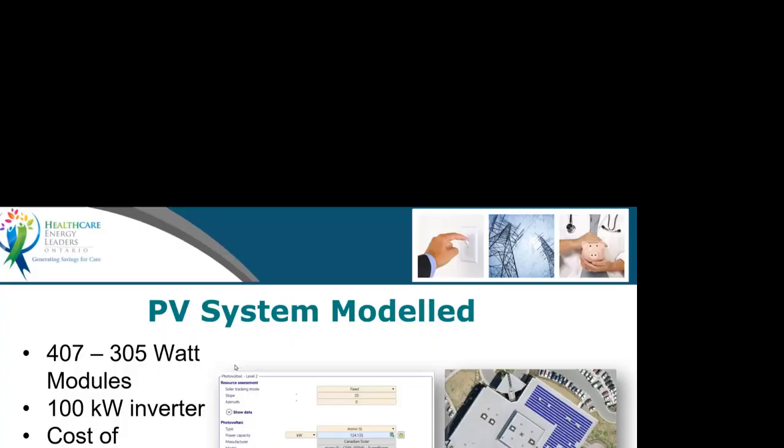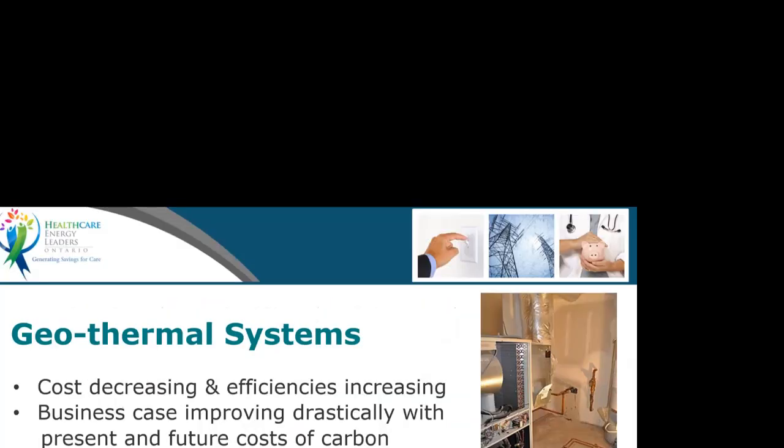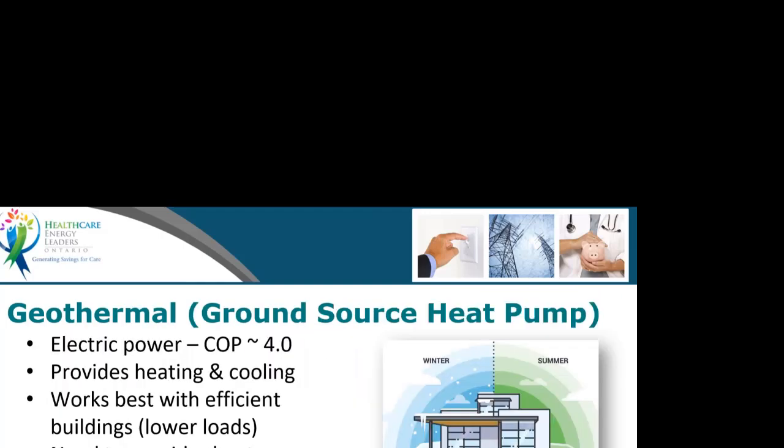Oh, this is one of my interesting ones. Geothermal systems, right? So here what we're doing is we're using heat from the ground, obviously, to introduce it into the building in some form or fashion and offset the purchase of standard systems, a heat pump system, basically, right? Not saying we're building a building beside, like, the heat geysers or whatever. No, this is really just taking heat from the ground at a relatively low temperature and raising the quality of that heat up to a higher temperature so we can use it in the facility and provide cooling at the same time.